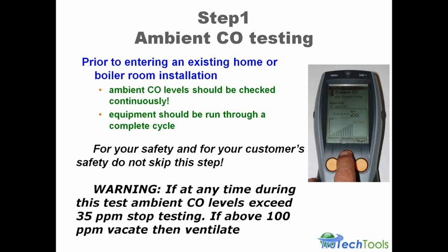All right, so now that we got past my intro warning here, let's talk about what step one is. Step one, when you walk in, you're going to do a combustion test. You got to realize a combustion analyzer like the Testo 330, Testo 327, I think even the Bacharach will do this, an ambient CO test.